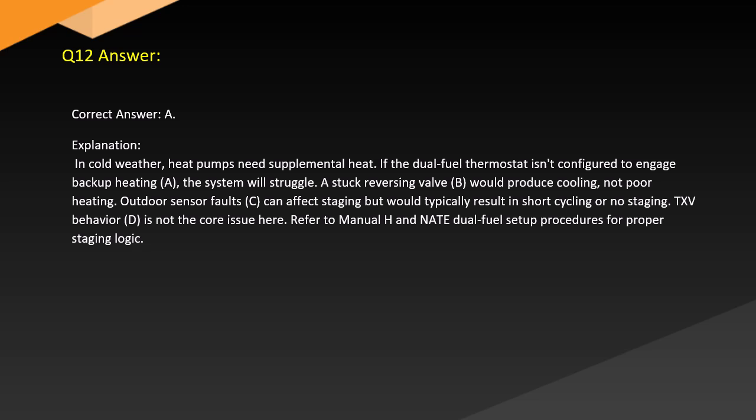Answer. Correct answer A. Explanation. In cold weather, heat pumps need supplemental heat. If the dual-fuel thermostat isn't configured to engage backup heating (A), the system will struggle. A stuck reversing valve (B) would produce cooling, not poor heating.